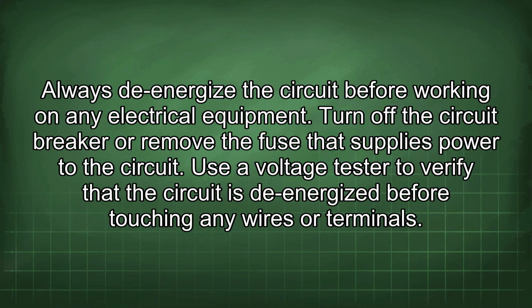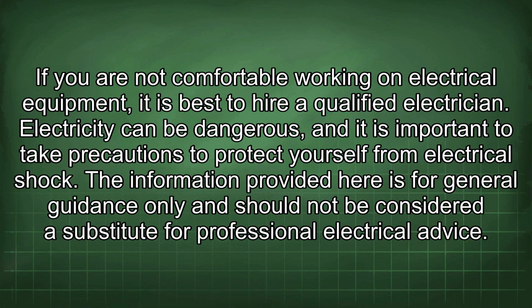Always de-energize the circuit before working on any electrical equipment. Turn off the circuit breaker or remove the fuse that supplies power to the circuit. Use a voltage tester to verify that the circuit is de-energized before touching any wires or terminals. If you are not comfortable working on electrical equipment, it is best to hire a qualified electrician. Electricity can be dangerous, and it is important to take precautions to protect yourself from electrical shock.